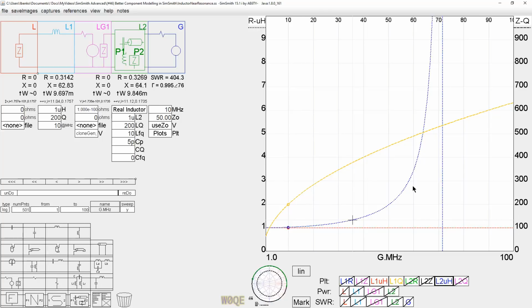We look at the Q on the circuit with the capacitor, or the included capacitance, and what we see is it rises just like the original one does, but it starts to fall off. And clearly the Q goes to 0 at resonance, and then back up again here. This is why I had the absolute value in there, because on this part right here, this inductor actually is capacitive. And this is kind of an interesting thing.